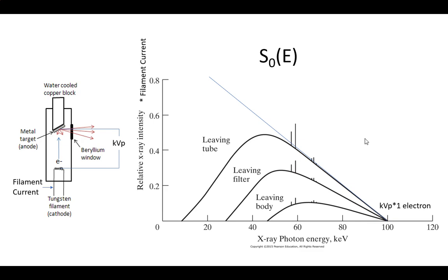So if you imagine the filament in the middle, they're going to want to come out pretty straight. Once they're going straight, the field will keep pulling them straight. They're not going to diverge as much. So we put that cup in so that the negative voltage we're putting on that side, what makes it the cathode, is also able to channel the beam. So in addition to accelerating it, by changing the shape of it, we are also able to cause the beam to go in a particular direction we care about.